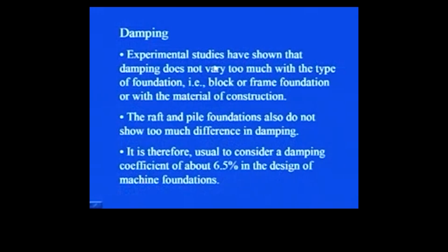Then experimental studies have shown that damping does not vary too much with the type of foundation, whether it is block foundation or frame foundation, or with the material of construction. Whatever the material of construction, be it concrete or any other material, or whatever the type of foundation, be it block, box or wall foundation, the damping does not vary much.